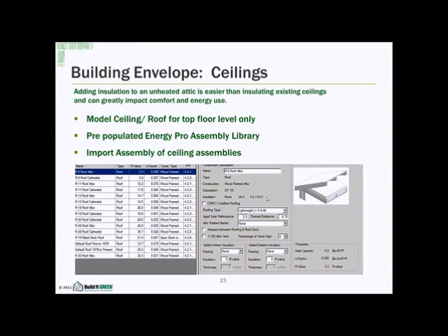So some additional information about the roof that's pretty important, especially if you're dealing with a cool roof or radiant barrier. So there's the CRRC-1, or the Cool Roof Rating Council Certified Roof Rating. You want to check that, and you want to put in the solar reflectance and the thermal admittance, and it should fall in your jurisdiction's energy code. So there are going to be compliance standards for if it's a low slope or steep sloped roof, and what those compliance metrics or requirements are for those types.